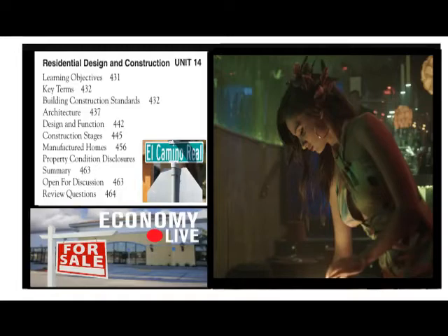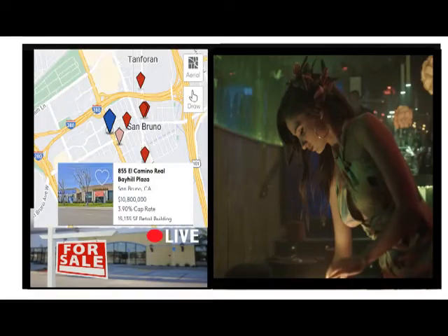Framework. After the foundation has been prepared, the house frame is erected. The frame is the skeleton to which the exterior and interior walls are attached. The frame consists of vertical supports called studs, which local building codes require to be no more than 16 inches apart. Short, horizontal pieces of wood are placed between the studs at intervals to act as fire stops by blocking air drafts. In platform frame construction, the frame of a multi-story house is built one story at a time, with each story supporting the next. Figure 14.4 shows the components of a platform frame system.